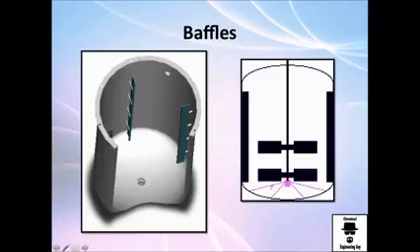Baffles, why do we want baffles? To increase mixture. So imagine you are moving and then you get stuck at this point right here, because as you can see it's literally a wall. So you generate more mixture and then go, and then crash again, and then move, and do it until, instead of just watching this little guy going in a radial way, very beautiful, you're going to have a chaotic path.